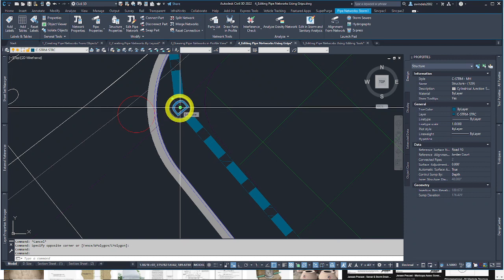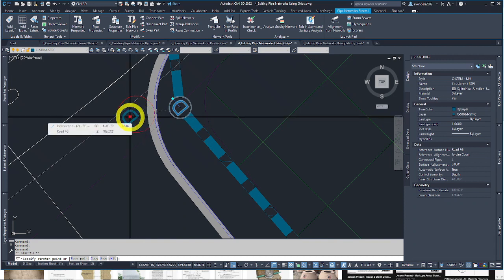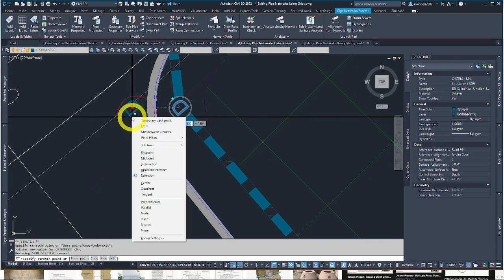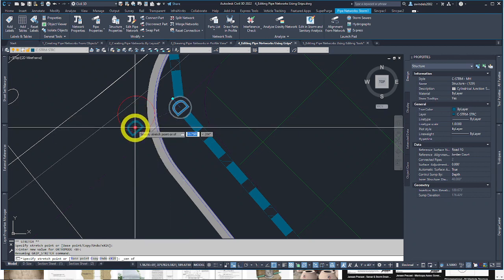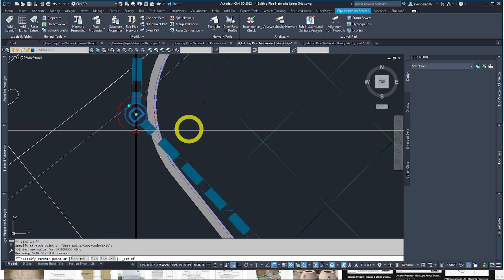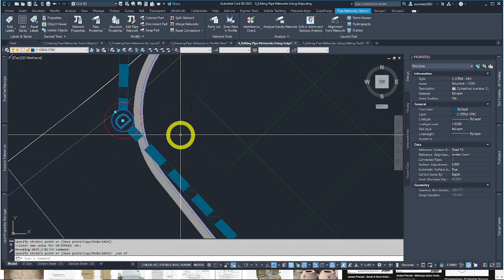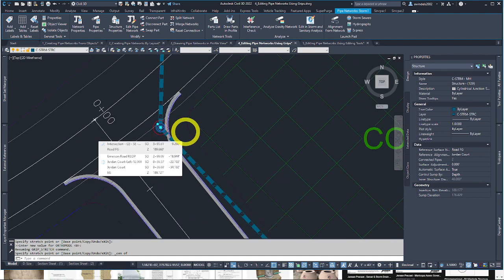We're going to do it in the top view. We'll move this, pick here, make sure your OSNAP has center turned on. So I have the Civil 3D pipe structure selected. I'm going to do the shift plus right click method and just pick center for one operation. Hover, we got to get the center to show. There we go. I moved the pipe network to my more favorable curb location is all I did there. And move on from that.